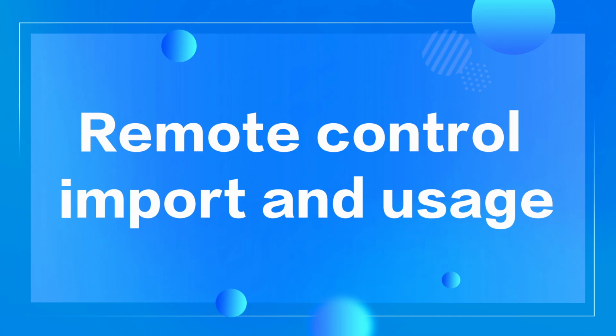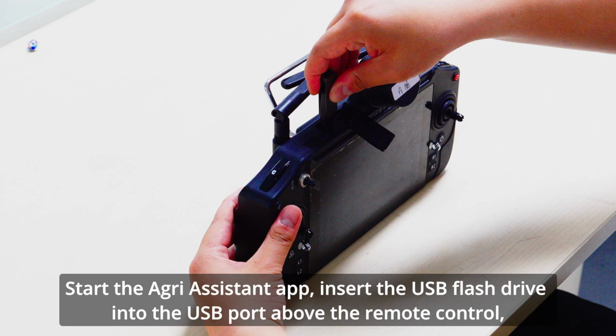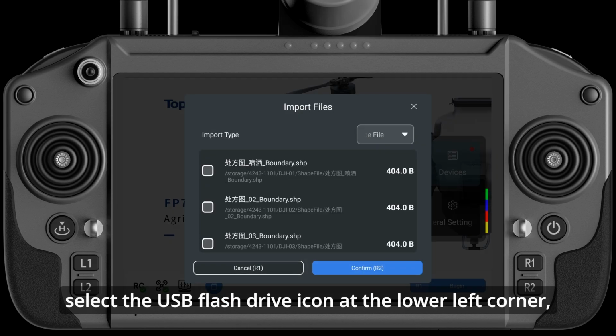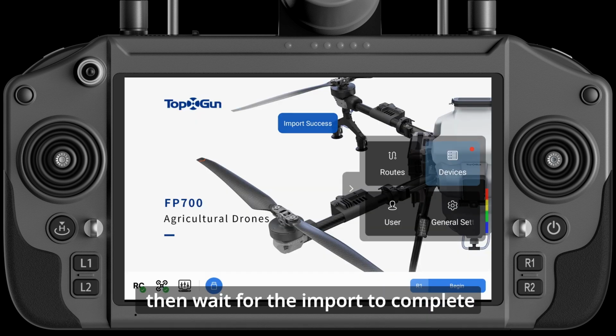Remote control import and usage. Start the Agri Assistant app. Insert the USB flash drive into the USB port above the remote control. Select the USB flash drive icon at the lower left corner. Choose Shapefile. In the import type, find the corresponding boundary name plot and click Confirm. Then wait for the import to complete.